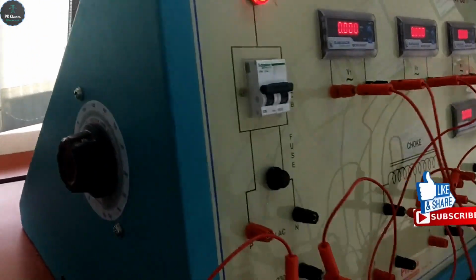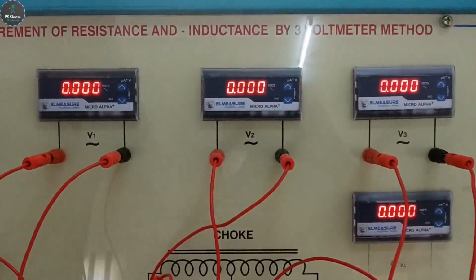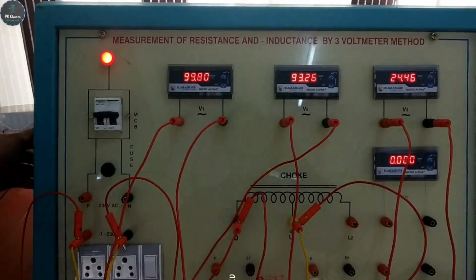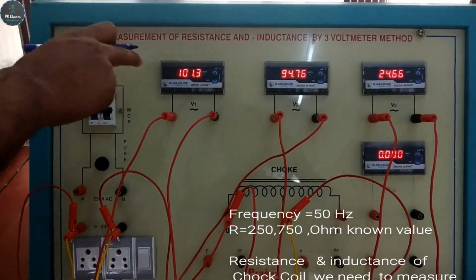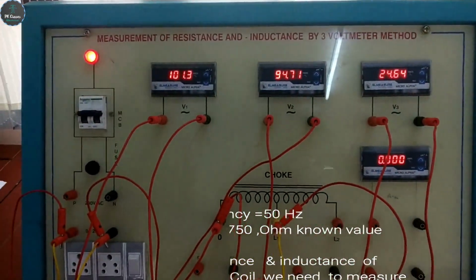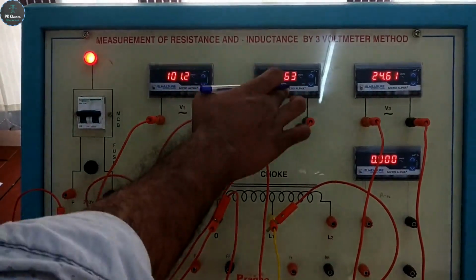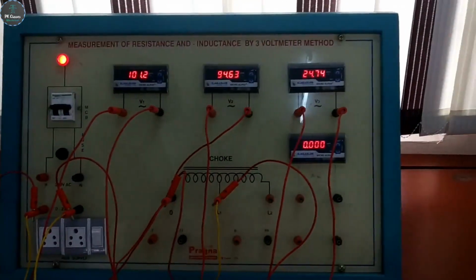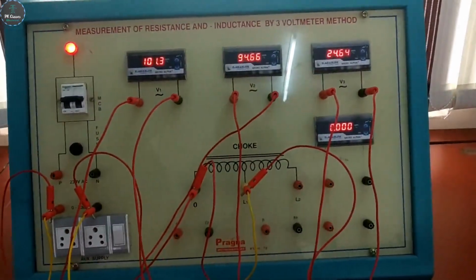So we connected everything. Before taking the reading, the auto transformer must be at 0 position. See here, all the voltmeters read 0 value, because we have not given voltage, right? So I will vary the auto transformer to 100 volts. I have given supply voltage 101.3. Just note down the supply voltage reading, 101.3. And VR, the voltage across this rheostat, is 94.63. And V choke is 24.81, right?